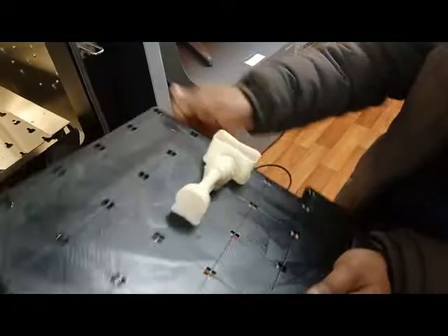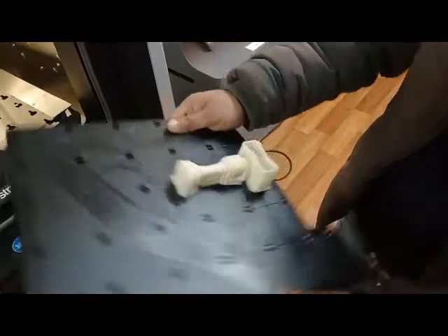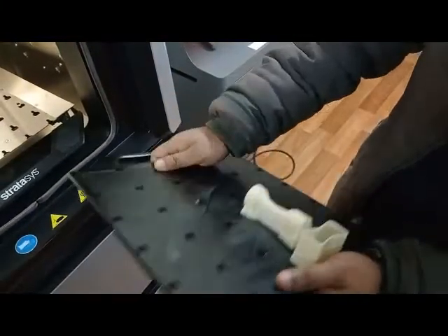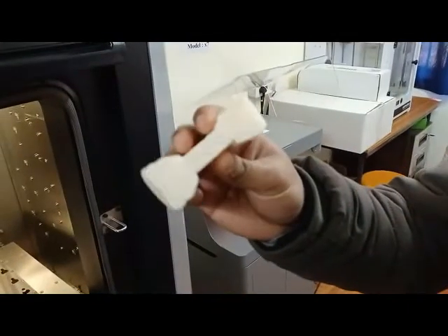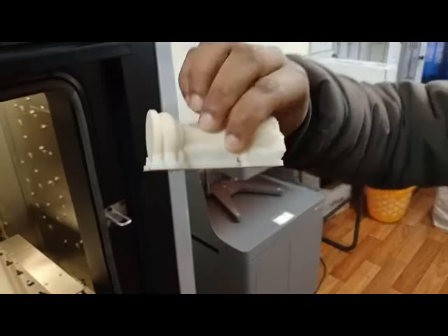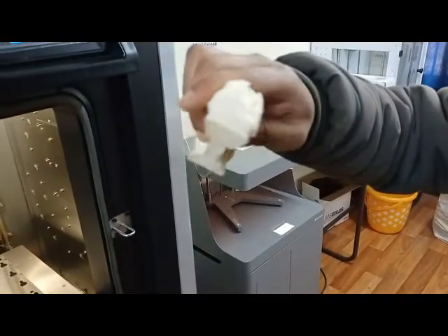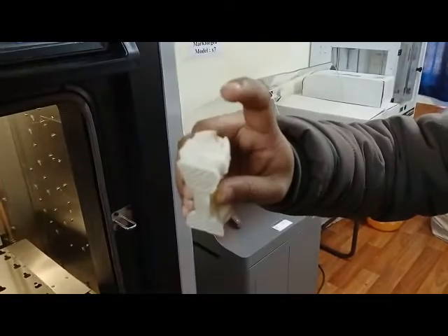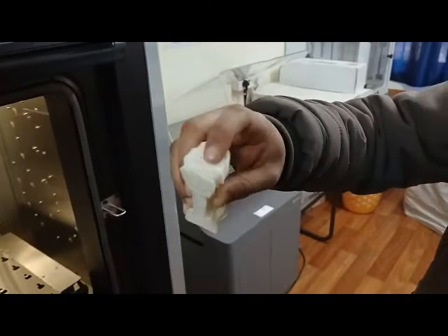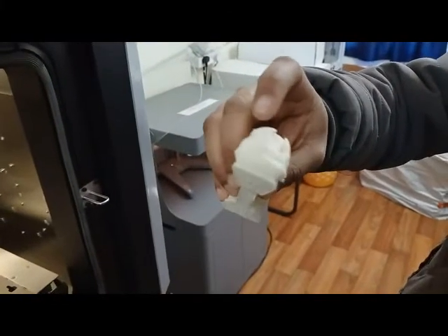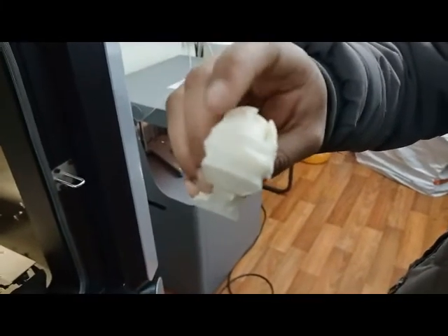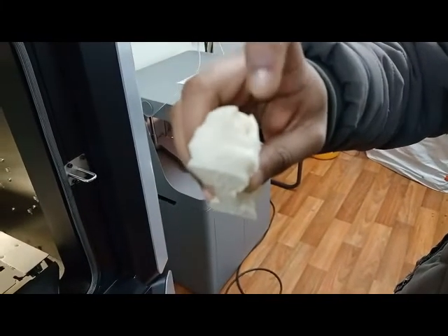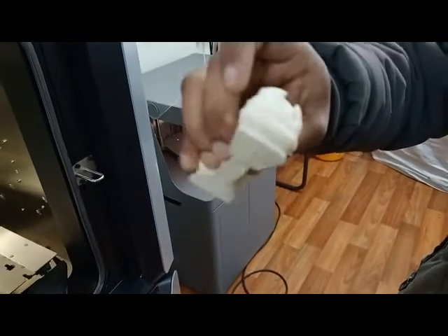So what we will do is that we'll just give a twist here, fine, in this way, so that it simply comes out. So this is the way it comes out, and you can say these are the support we have here. So this much layer of support is required, and even here we have some integrated shapes here. Some complex shape was given in the head. So also in the head you can see it is almost 80% covered with support material, so as to give the support to the complex parts, fine.